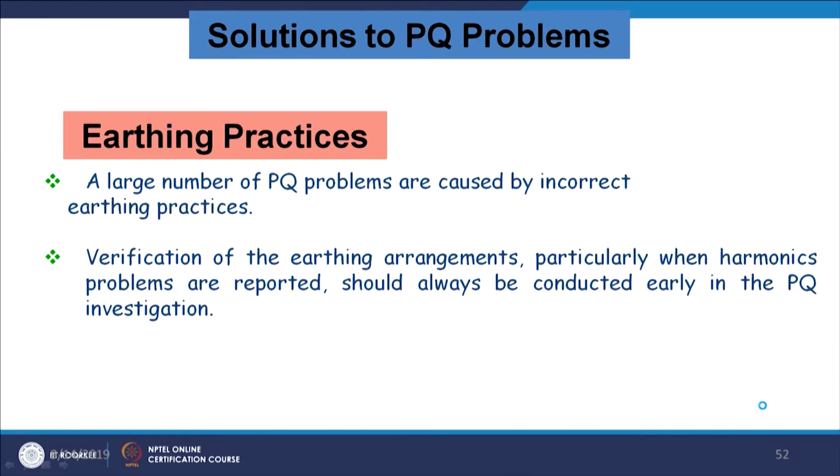Another is the earthing practice. This is also an important entity. A large number of PQ problems are caused by inaccurate or inappropriate earthing. Verification of the earthing arrangement, particularly when harmonics problems are reported, should always be conducted early in the PQ investigation.